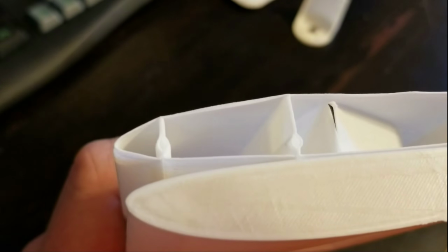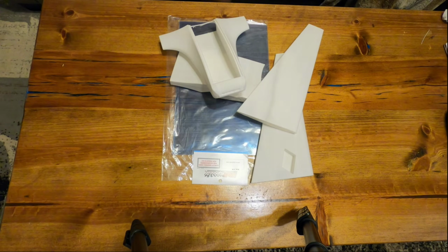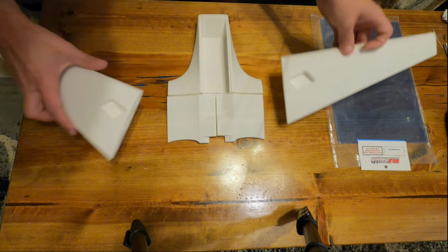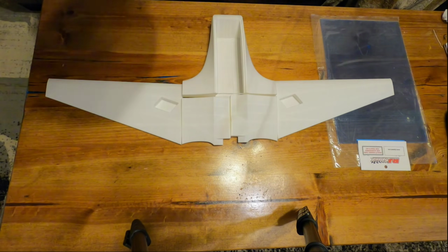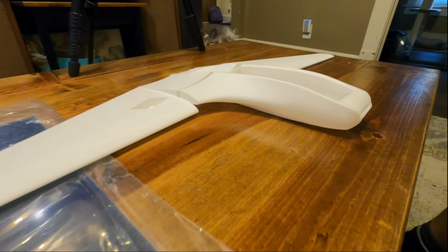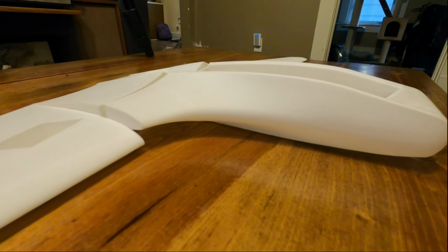A quick note on the LW-PLA material: this filament is a great option for 3D printed planes. The plastic foams up after extrusion through the printer nozzle, forming a much less dense part than fully solid print resins. It also finishes and adheres very well during the spiral vase printing.